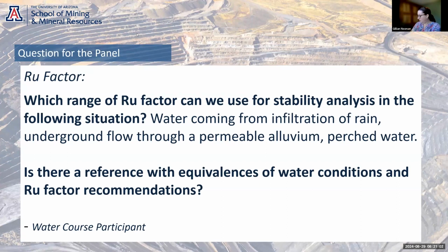Yeah. But RU again is essentially the ratio. It's not quite, but it's essentially the ratio of the downward force to the upward force. It's not quite that, but that's a simple way of saying it. And because the weight of the rock is typically twice the weight of water, again very simplified, the RU for hydrostatic conditions, so if you have a situation where the water table is at the surface, is about 0.35, so about a third. So that's a typical RU for hydrostatic conditions.